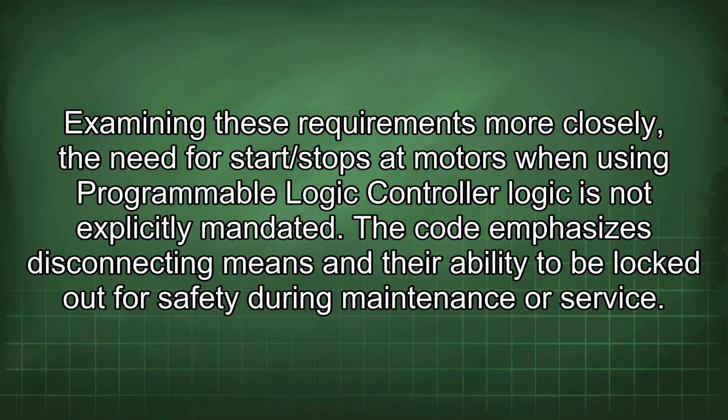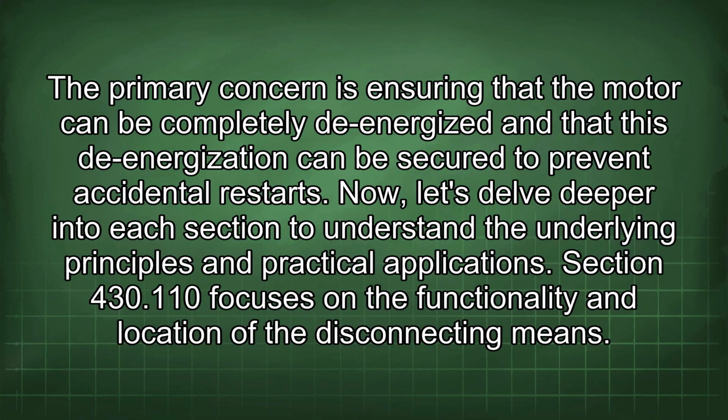Examining these requirements more closely, the need for start/stops at motors when using Programmable Logic Controller logic is not explicitly mandated. The code emphasizes disconnecting means and their ability to be locked out for safety during maintenance or service. The primary concern is ensuring that the motor can be completely de-energized and that this de-energization can be secured to prevent accidental restarts. Now let's delve deeper into each section to understand the underlying principles and practical applications.